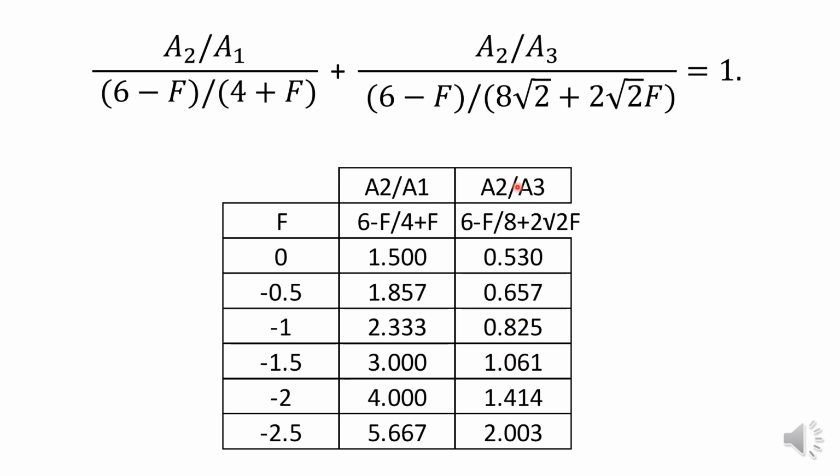So this may not be convenient for you to be too restrictive with this value of a2 over a3. So the -2 or the -2.5 may offer you more flexibility, more choice in the ratios. But this is just hypothetical, of course. I'm just asking you to consider this as a guide when you are designing these types of indeterminate trusses.